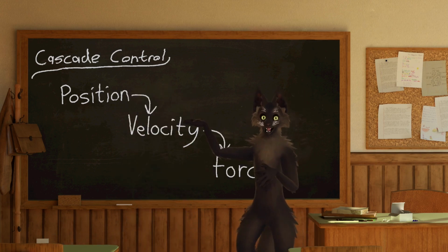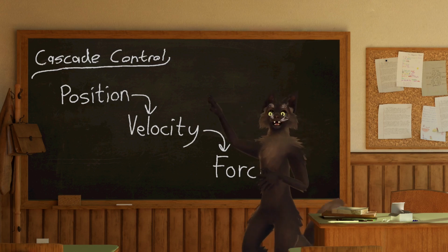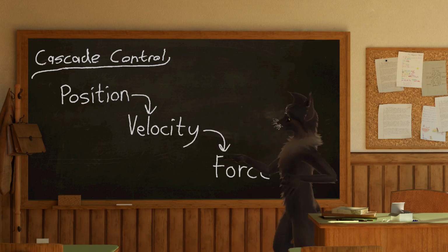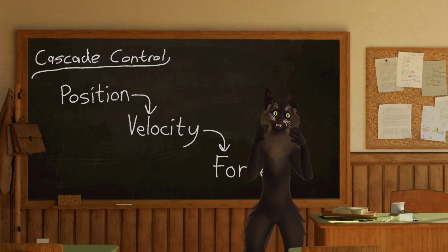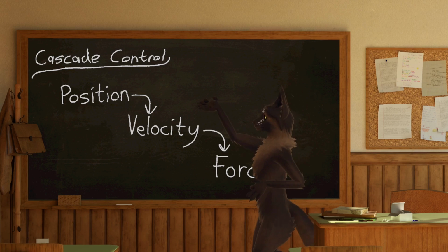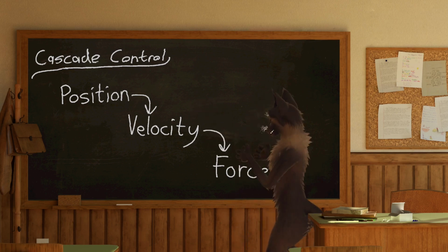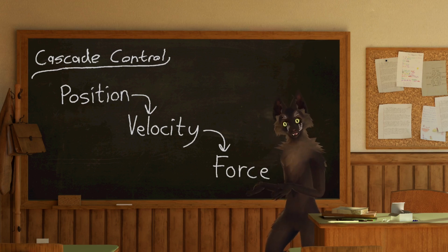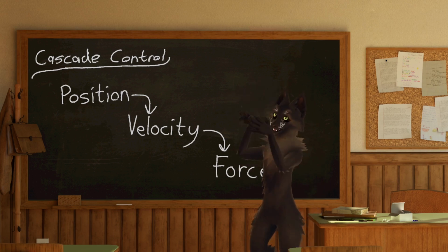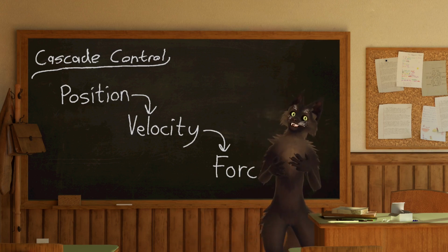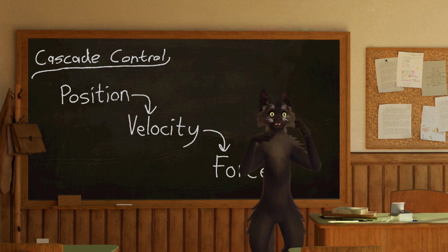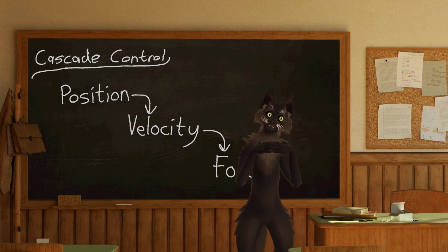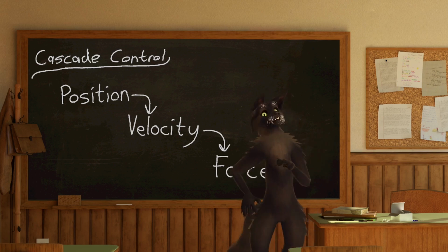So that's Cascade Control in a nutshell, but Cascade Control can get more complicated than this. This here is just a linear chain of controllers, but it actually does form a whole hierarchy, where you can have a high-level controller controlling multiple low-level controllers, and you can have a low-level controller that's being controlled by multiple different high-level controllers. And you can end up in situations that seem like they should come into conflict. The multiple controllers don't all work together, and they may not find a solution that's copacetic to all of them, but usually they can.